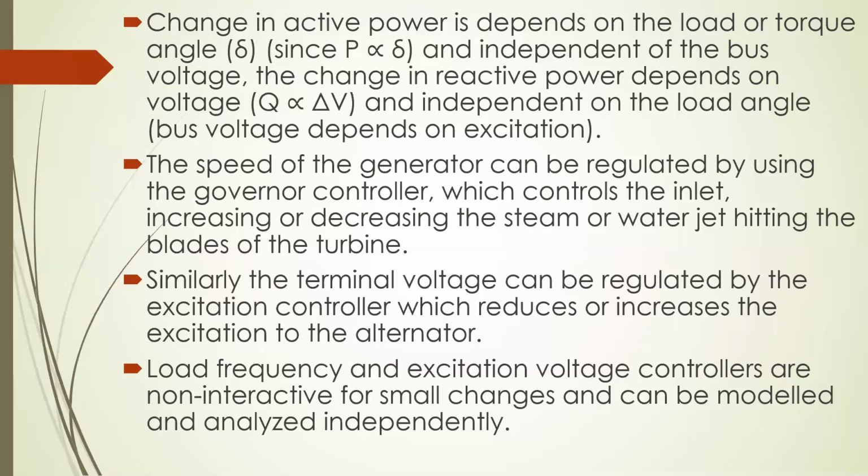So these two will not interact for small changes. These two will interact for large changes. So these less-interacting parts can be modeled and analyzed independently. Separately, we are going to analyze these two things. That means active power control can be analyzed separately, and reactive power control can be analyzed separately.